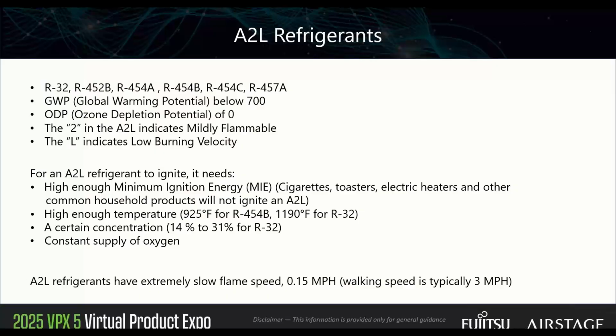For R32, it's 1190. So R454B will ignite at a lower temperature than, for example, R32. It needs a certain concentration, 14 to 31% for R32, and a constant supply of oxygen. If any of those 4 conditions aren't there, it's not going to ignite.